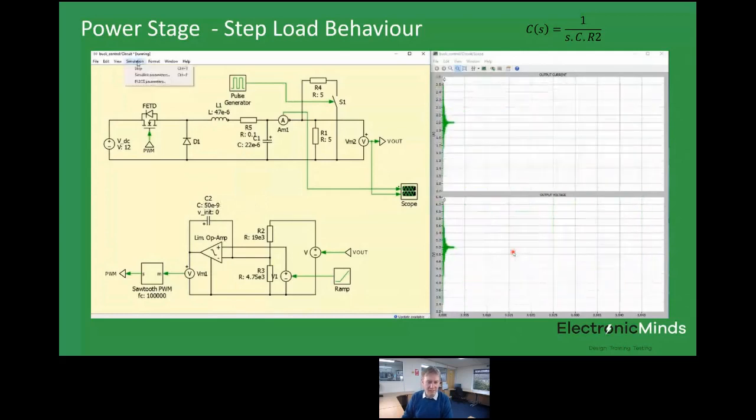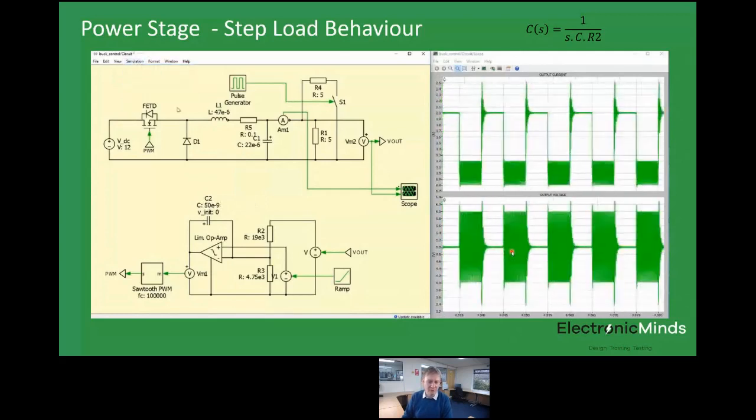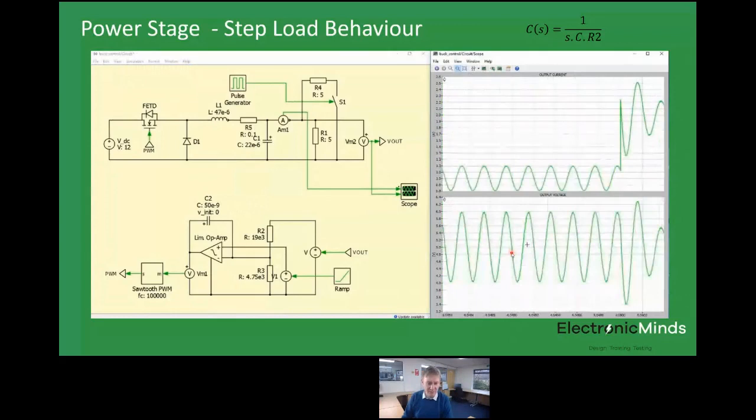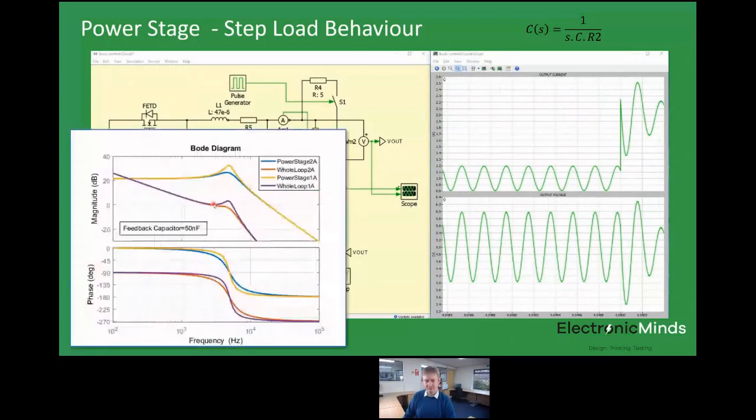And you can see here that under the light load condition down at 1 amp, we've actually got instability in the system. If we zoom in on that, you can see we've got classic instability in the closed loop system, because we played around with the frequency of that integral control to the point whereby the loop gain is just not stable anymore.